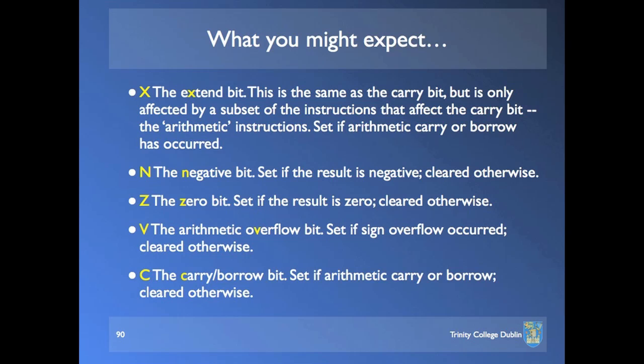One of them is the move instruction. If you look at the move instruction in your instruction set summaries, you'll find that it affects the condition code register as you might expect. When you see an asterisk in the condition code register summary for an instruction, it means that that particular bit, let's say the N bit or the Z bit, is affected as you'd expect, and as you'd expect we'll talk about in a minute. And a minus means the bit is unaffected. It retains its previous value. And there's 0 and 1, and there's U for undefined, left as an exercise to the reader.